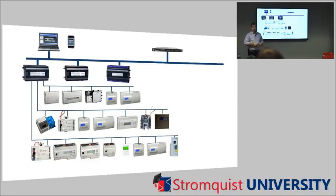But different manufacturers' Jaces, if they are Niagara Jaces, can talk to each other. Question, sure. For clarification purposes, can you or can you not take a BACnet device and put it on a LAN network? No, you can't. Well, you can or you can't, depending on how you want to, because we can put them into that Jace, and they can talk to each other, but I couldn't take this LAN controller and stick it on this BACnet network. It wouldn't know what it was doing because it doesn't talk that language.